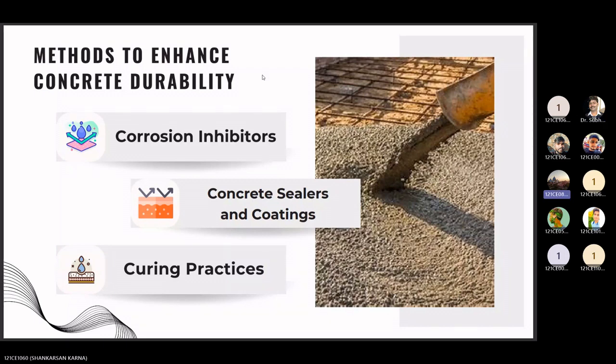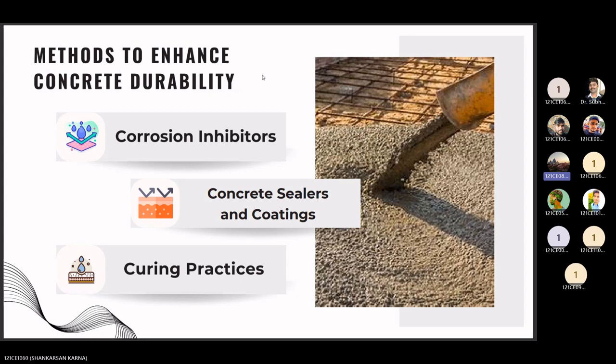Next one is curing practices. We can implement proper curing techniques to maintain adequate moisture and temperature conditions during the initial stages of concrete curing. Adequate curing promotes hydration, improves strength development, and enhances durability properties.